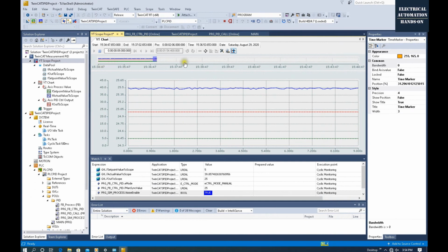So as we know, this is the overall picture of this online trend. If you want to check the actual value of the process value within this area, firstly, we can pause this trend. With the pausing, behind it is still working, we will see this value is still moving. Just this screen is paused. So we can resize this window and move this window. This window represents this area, how long and what the width of our time. We can move the window.